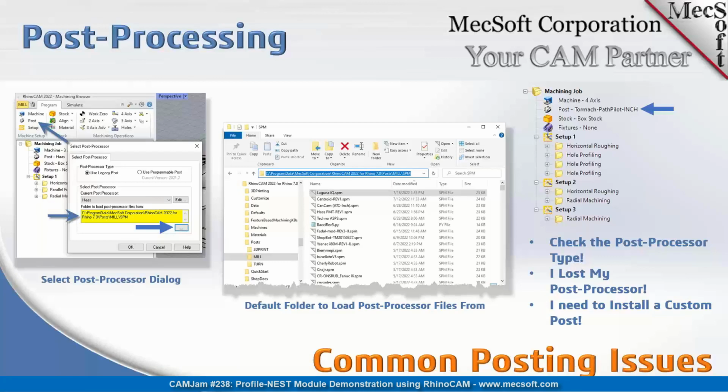Now, the next item here is I lost my post processor. We hear that a lot. Things can happen. This directory where it's pointing to your post processors, for some reason you could have changed it, or you could have a customized post and it's not showing up in your list and you can't find it.